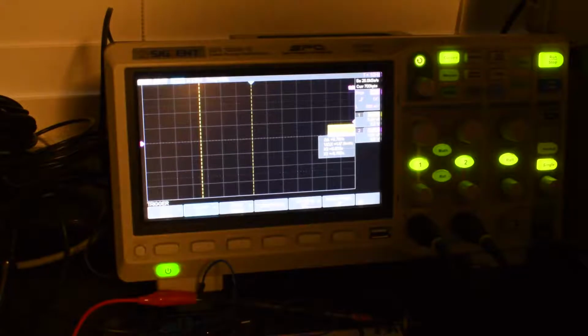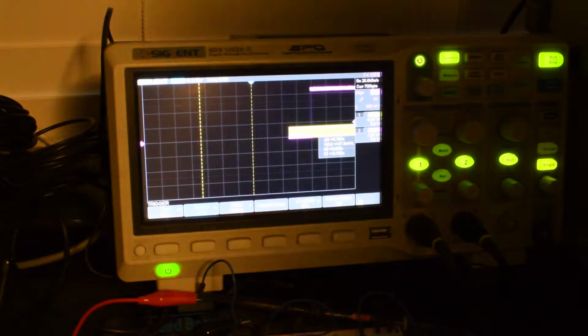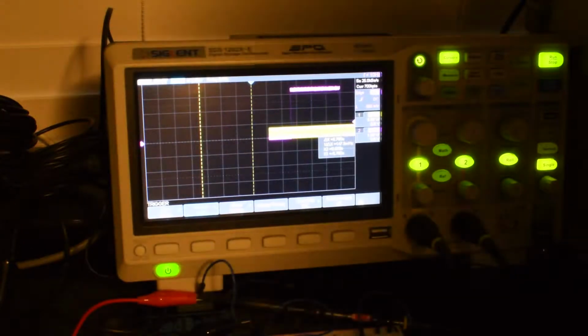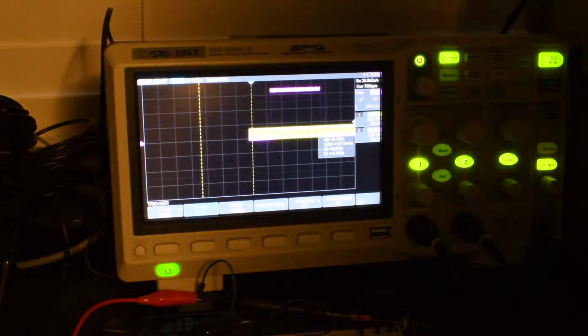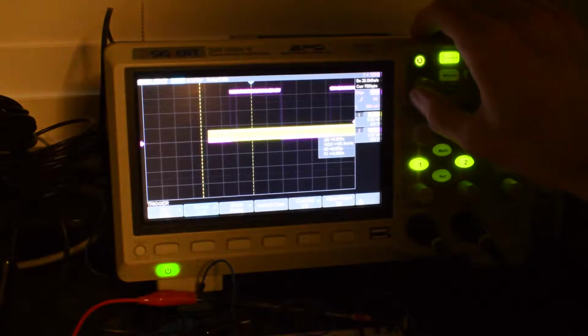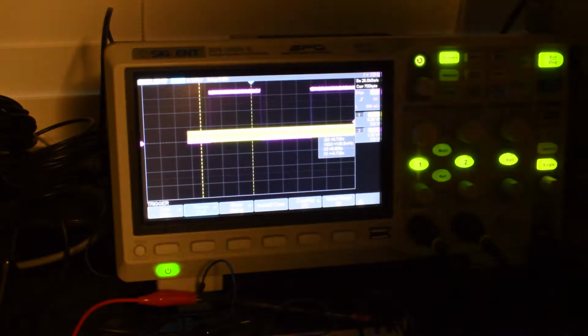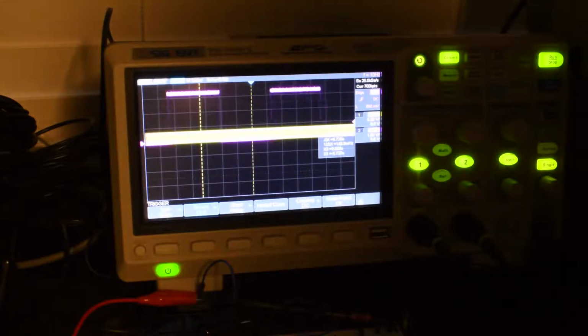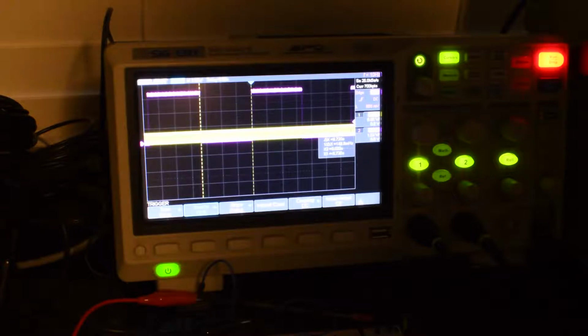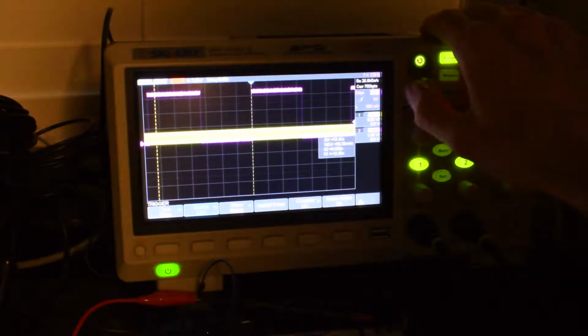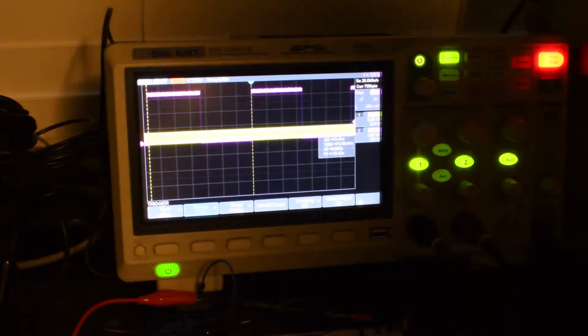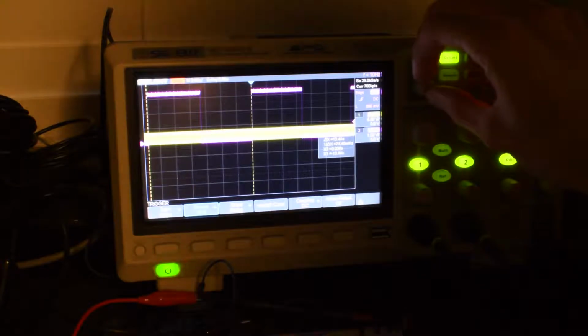when we're comparing the frequencies of the two oscillators is this one. So now it's still scrolling across in real time, so you can see it's much slower. So that's high for 6.76 seconds, I think, something like that. And the complete high to low cycle is going to be about 13.4 seconds. So if I measure the high and the low portion of one cycle, yeah, that's 13.